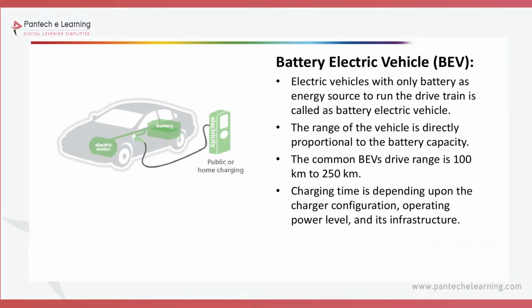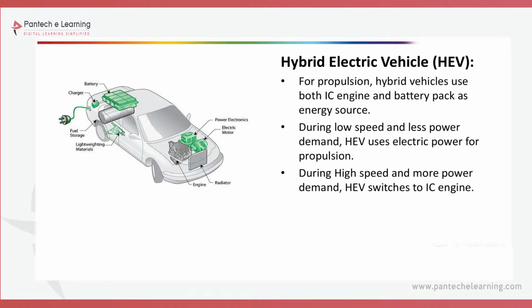Nowadays, the charging time depends upon the charger configurations, operating level, and infrastructure, and the capacity of the battery. Charging from 0 to 100% takes more than 8 hours. Charging to 50% takes 4 to 5 hours. So charging depends upon the battery capacity. So this is a BEV.